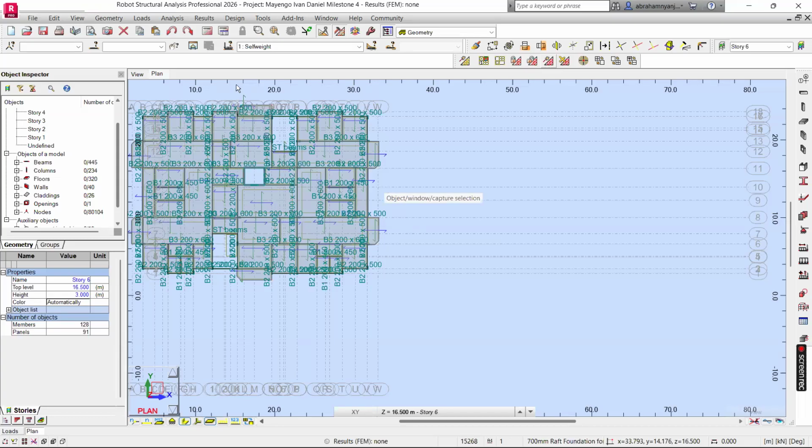What the software does, whenever you run the calculation, is recalculate self-weight for all the elements that you have in your model. So if you earlier introduced a new element and probably you don't see it showing the self-weight, you shouldn't panic, you just proceed. The moment you reach the time of running your calculation, the software first runs the self-weight throughout all elements, it recalculates the self-weight.